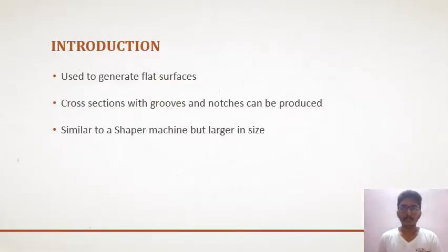Introduction. Planing machines, which are also called as planers, are similar to shaping machines, but these are larger in size and larger workpieces can be machined using this. Planing machines are generally used to generate flat surfaces. Besides these, cross-sections like grooves and notches can also be produced.